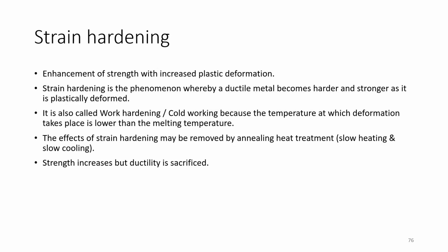Next is strain hardening. It is work hardening, strain hardening, or deformation processes. These all three are almost similar. It is the enhancement of strength with increased plastic deformation, a phenomenon whereby a ductile metal becomes harder and stronger as it is plastically deformed. It is also called work hardening or cold working because the temperature at which deformation takes place is lower than the melting temperature. The effect of strain hardening may be removed by annealing heat treatment, which is slow heating and slow cooling. Strength increases but ductility is sacrificed.